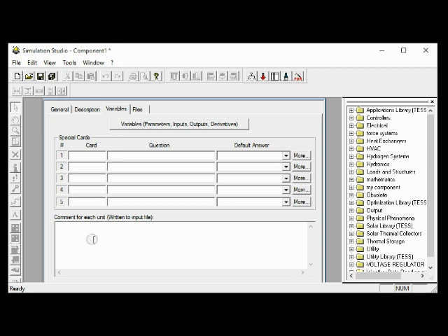This special card can be inserted into the Trnsys input file by the use of the special cards section, which is also accessed through the variable tab of the proforma. An example of the use of special card section will be seen in the plotter when we start to use our newly created model within the assembly panel window.